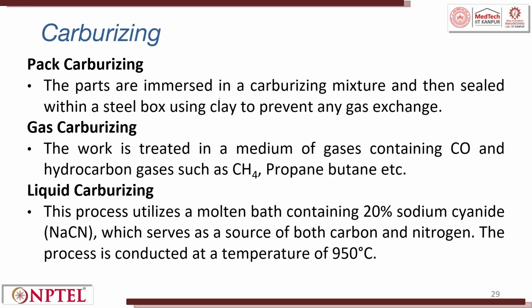In pack carburizing, the parts are immersed in a carburizing mixture and then sealed within a steel box using clay to prevent any gas exchange.